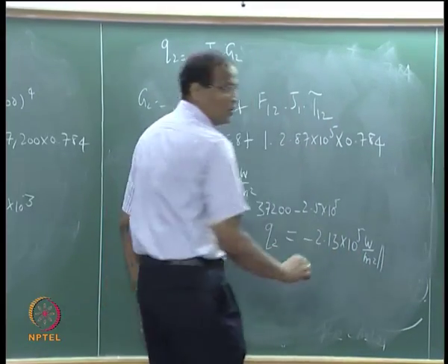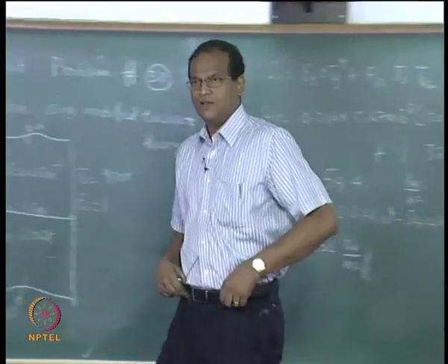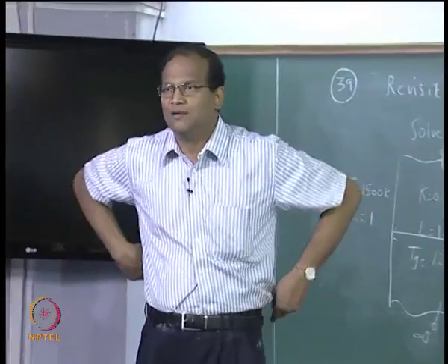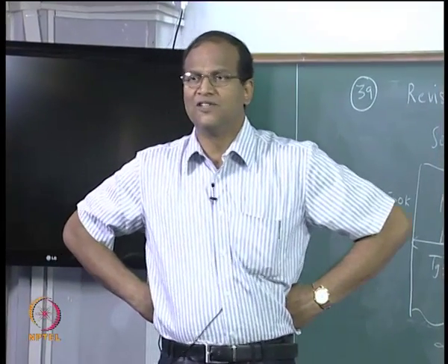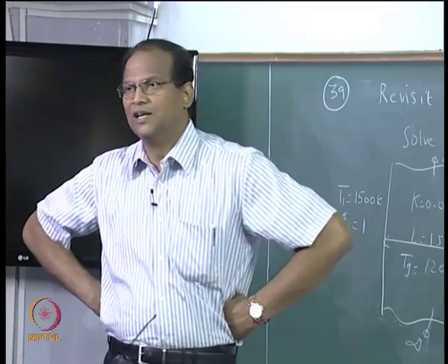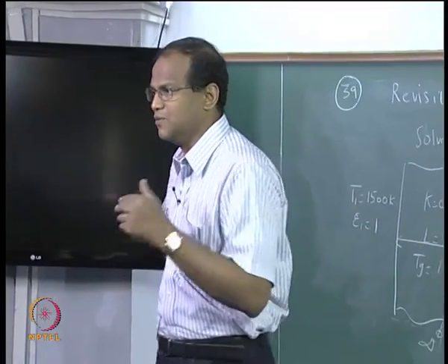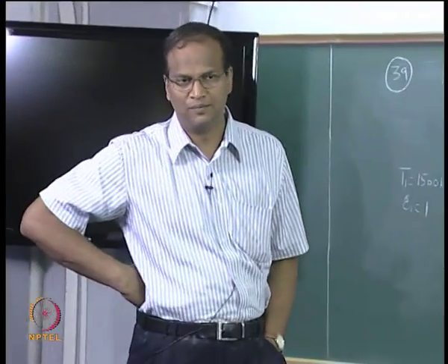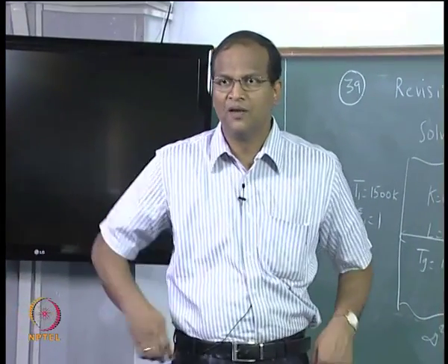So if you are given a black enclosure or a problem involving two black surfaces, parallel plate formula, you can either use the analytical method, I mean get the solution, use the solution, get the exponential integral, or you can use the theory of evacuated enclosures to solve the problem. Okay.